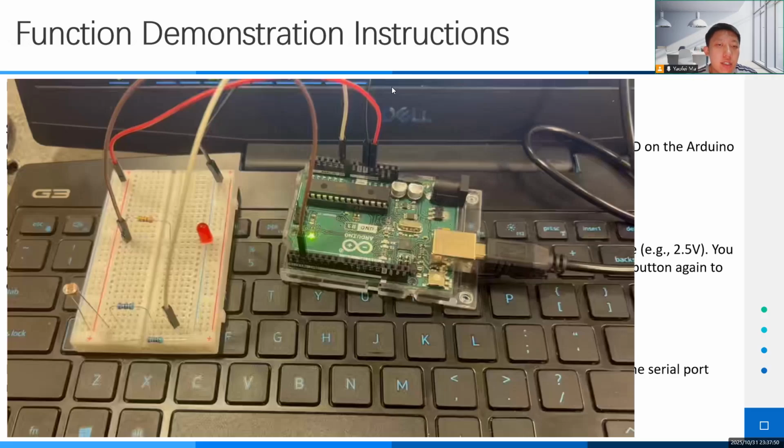Now let's see how to use the project step by step. Step 1. Toggle the LED. Make sure Arduino is connected to the computer and the C# application is open. Click the Toggle LED button. The label shows LED state toggled. Look at the Arduino board. You will see the LED turn on or off. It flips each time you click.